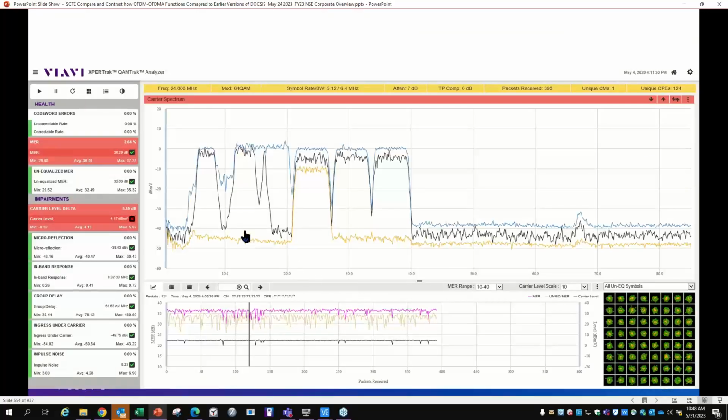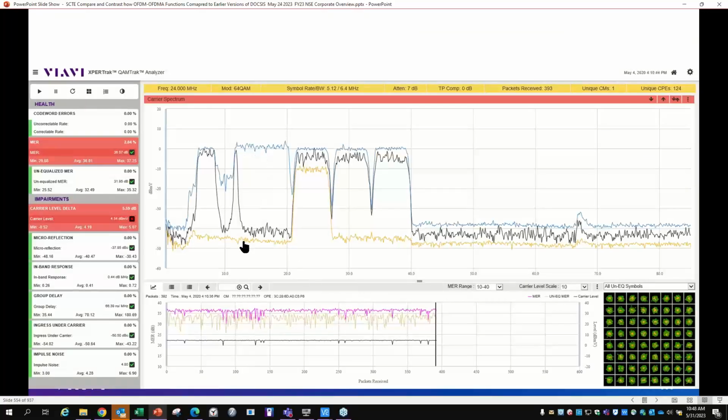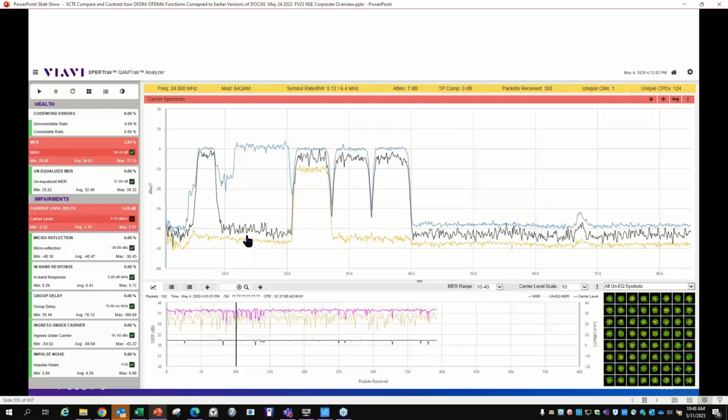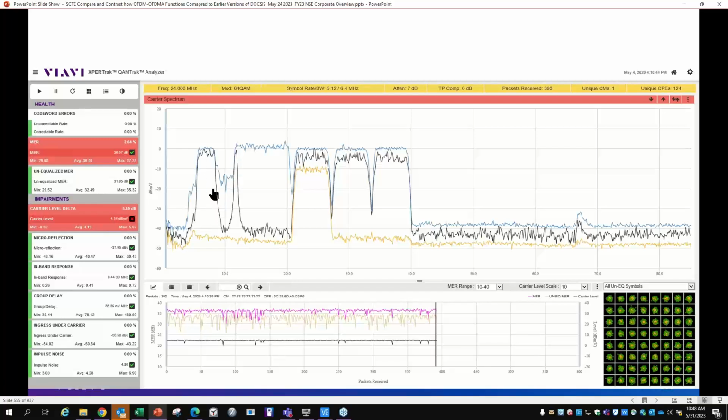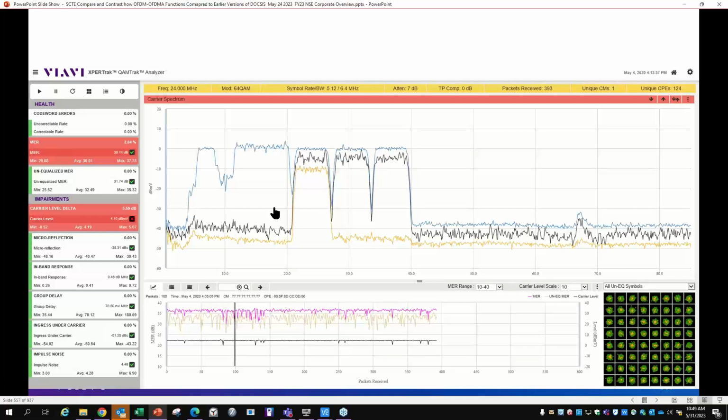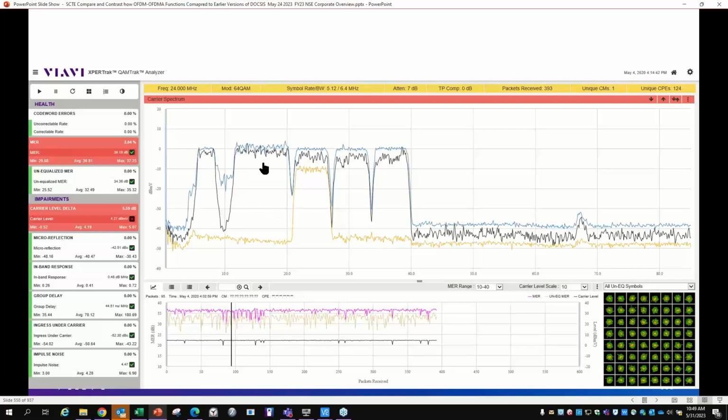Here's an example. I'm just using an example, but watch how the mini slots work, right? So right now, it's a possibility, obviously a high possibility, that a modem is transmitting on all of these carriers themselves, and it's using this portion of the OFDMA carrier, right? This is the exclusion zone for the set-top box. So as the traffic is embedded, at this point, it's using all of the upstream traffic.